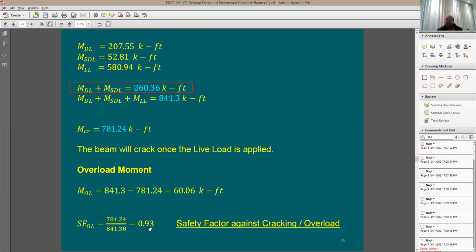Now you think, if I have here additional load of nearly 50% of the given loads, which means the demand, the beam is going to be right there at the cracking point. So if my intention is to have an uncracked beam, I'm going to be very satisfied with a factor of 1.5, because with 1.5, I still have a long way to go in terms of the loading.